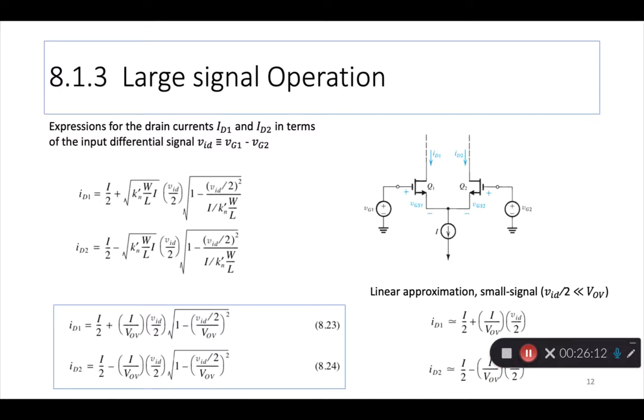The same thing keeps appearing again and again. We are interested in something called the overdrive voltage, which is always the gate to source voltage minus the threshold voltage VT. Then we have a formula for drain current, ID, which is generally half, and then it depends on Kn prime, W by L, and so on. So the same voltages, if you keep flipping them around, is what you see happening in all these analyses.